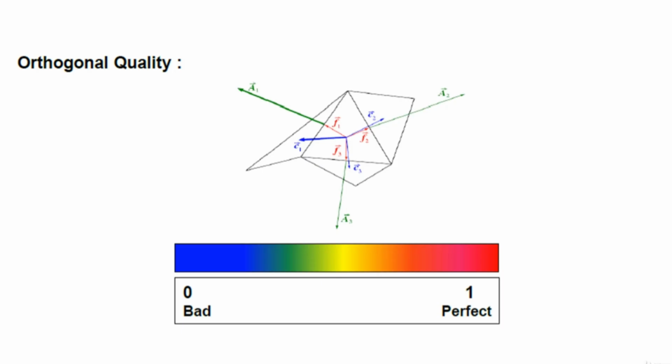And these are the different quality metrics that are used to study the quality of the mesh that is generated onto this particular geometry. Then remember, all of these things are based upon the type of geometry you are meshing and the type of accuracy you require, and it all depends on a lot of other factors.